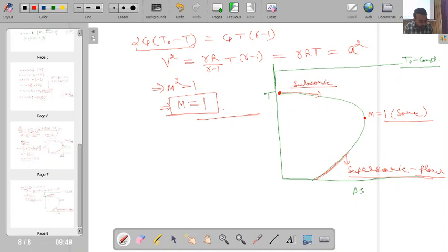And in case of a supersonic flow situation, if you start at this point and move along the length of the pipe, say for length L1 you get this point, and if you further increase the length to L2, you get this point. If your length becomes the maximum possible length, then your Mach number is equal to 1.